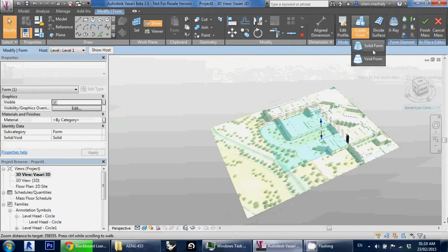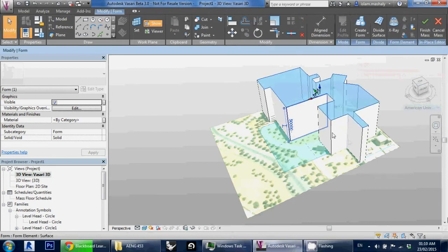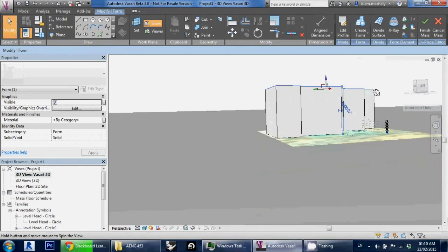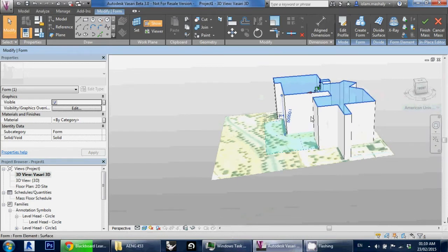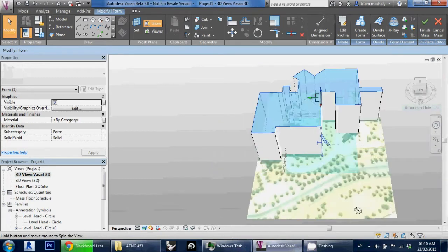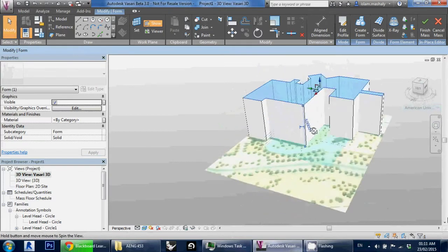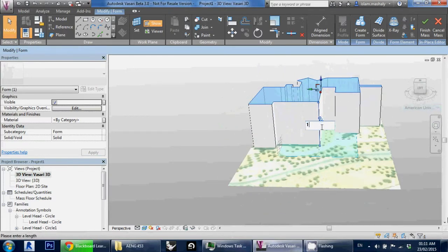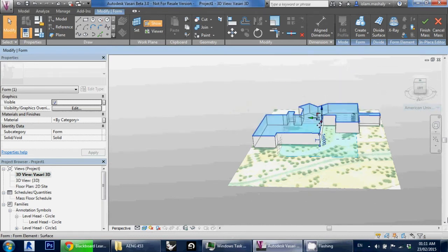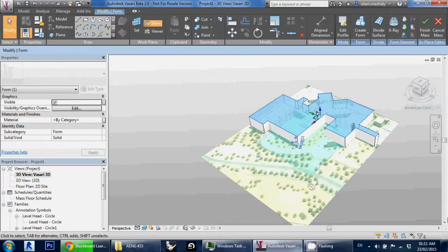The next step here is to create the solid form, and I have to make sure that the solid form is accurate. It must have the same height as the buildings. If this is the SSE building, we know that it has 3 floors, and it's around 13 or 14 meters if I remember correctly. So we're going to make this 14 meters, for example, like this. And this is a footprint of the part that is related to our site for the SSE building. And we're going to have our site in this place, for example.